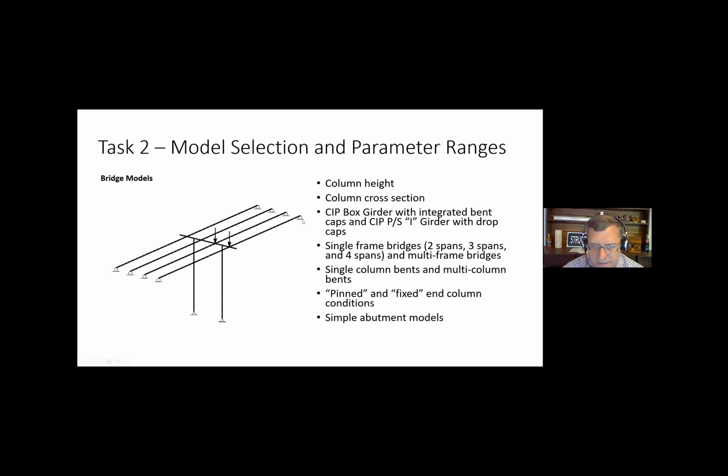So, one of the big questions is, with seat type abutments, can the vertical loading induce sway to where we engage the sidewall or the back wall, and then how does that affect the overall strength of the columns under heavy vertical loading, or slender columns under moderate vertical loading.